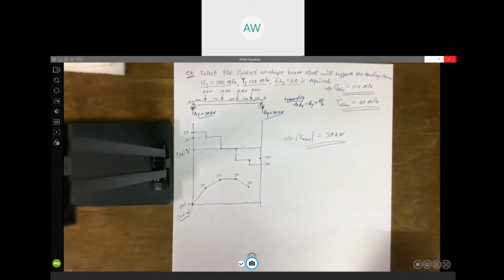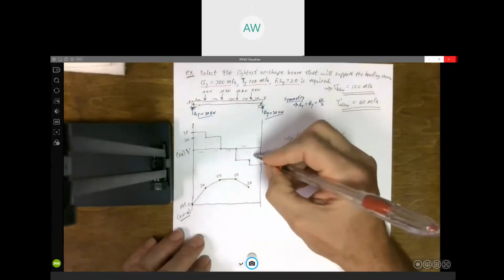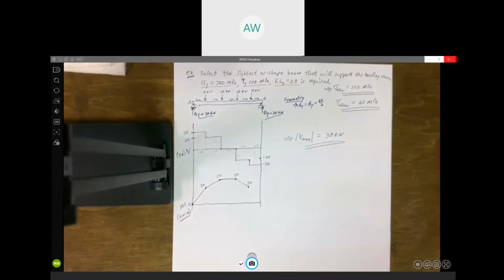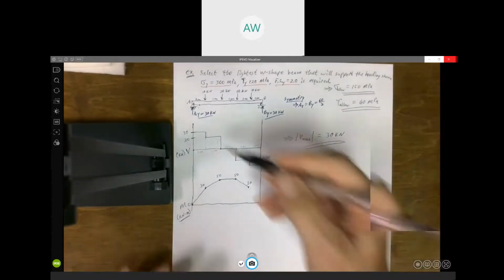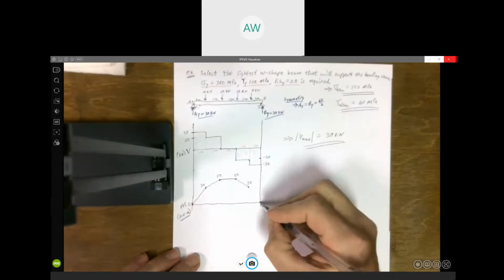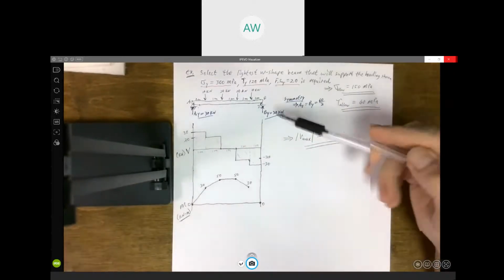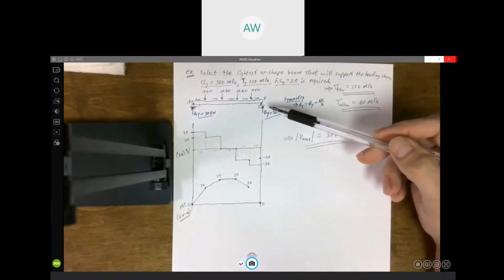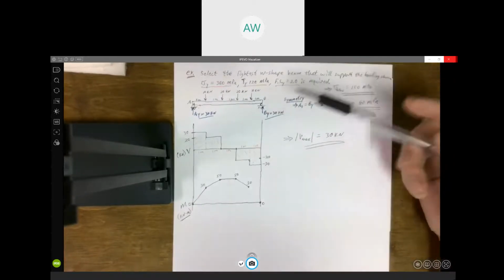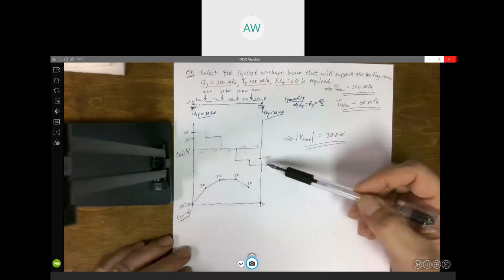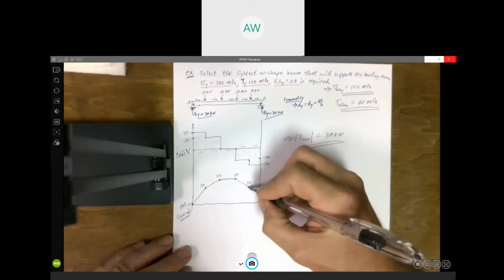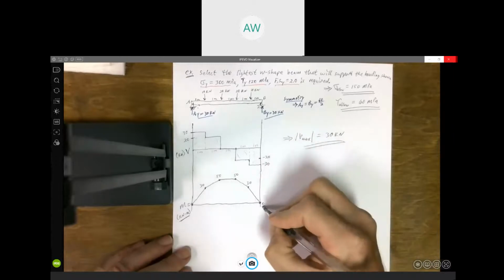And now finally, we're going to go down this area, which better put me back to 0, because the same reason the moment was 0 at that end of the beam, the moment better be 0 at this end as well, because there's no moment there. It's a roller support. A roller can't provide a moment, and there's no applied moment. And in fact, if you look at the area, 30 times 1 is negative 30. We're going down 30, puts me back at 0.